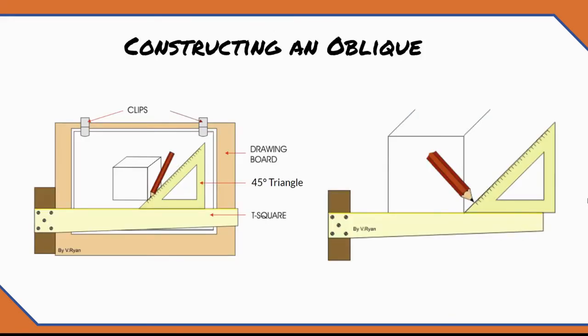Creating an oblique drawing using a grid can be a little tricky. For these, we use a standard orthographic grid with vertical and horizontal lines. The problem is with drawing the depth lines, since they are drawn at 45 degrees. The most accurate way to do this would be without a grid, using a T-square, a 45-degree drawing triangle, and a ruler. Then you would be able to draw your 45-degree depth lines at exactly the right length.